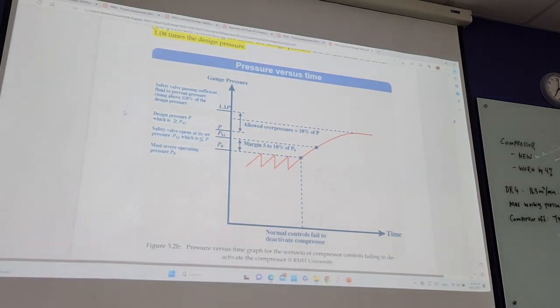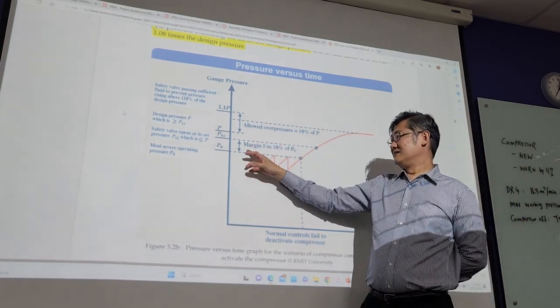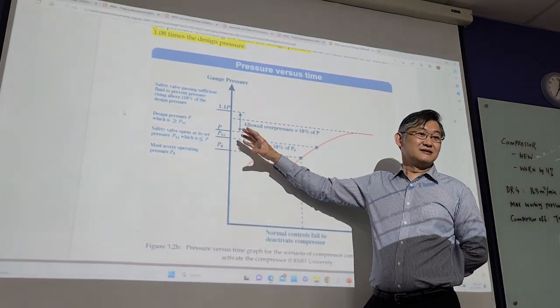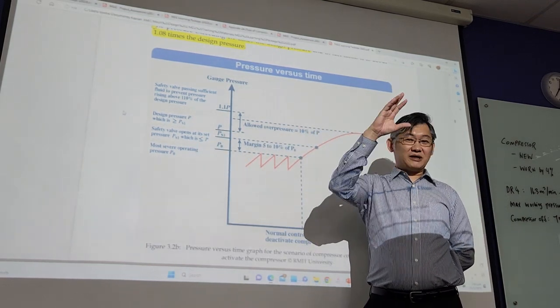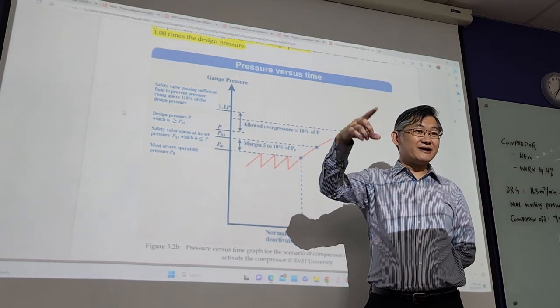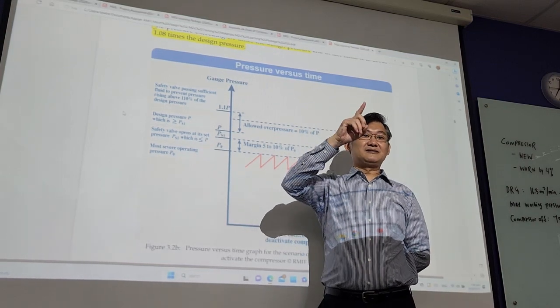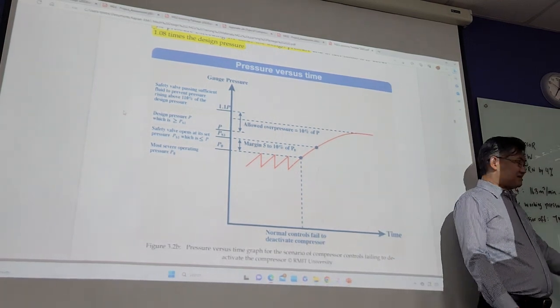So it's quite close, right? Because 10% is about 9.9%. As long as it is between 5 to 10%, it is acceptable by the authority. This is actually set by the authority, the Australian Standard. They determine 5 to 10% is considered safe because we don't want our pressure to increase to that level. First is 790, your compressor works and stops. But if your compressor fails and keeps pumping pressure, we want to make sure the safety valve is installed such that it will release pressure at 862, very close to 10% of our set pressure.